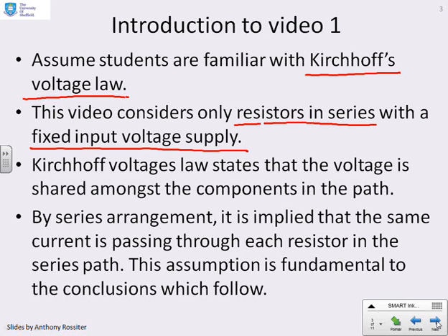Now, Kirchhoff's voltage law states that the voltage is shared amongst the components in the path, and again we'll clarify what we mean by that in a few slides' time. And by a series arrangement, we mean that the same current is passing through each resistor in the path. Now this assumption is fundamental to the conclusions which follow in the next few videos.